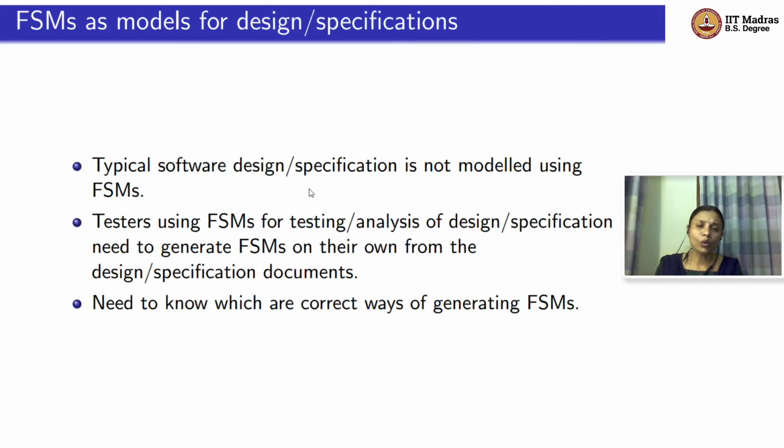So how do you model state machines? This is a tricky problem. Typically, it cannot be taught within the scope of one or two lectures like this. Typically, we don't model a full code or specification using a finite state machine. We abstract the features that we want to model, check for ourselves whether we can model it as a finite state machine, then go about modeling the finite state machine. This needs some practice on how to generate correct finite state machines, and you can run simulations to check if they are correct or not.